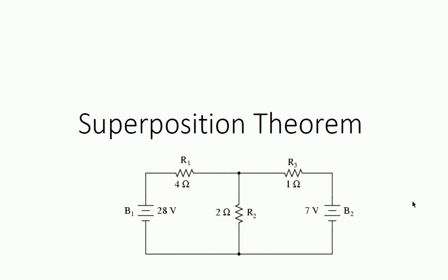Just to give you a warning, that resistance is not a constant value. The more current you draw, it seems to change. I did some tests on various batteries, and you can try it out yourself. If you draw 1 amp out of a battery, you get a certain amount of voltage drop. The internal resistance is the voltage drop divided by the current, so R is equal to V divided by I. If you then draw 2 amps out of it, what you find is that the value is actually going to change. It's not a constant. So again, bear it in the back of your mind. But anyway, that's what this represents.